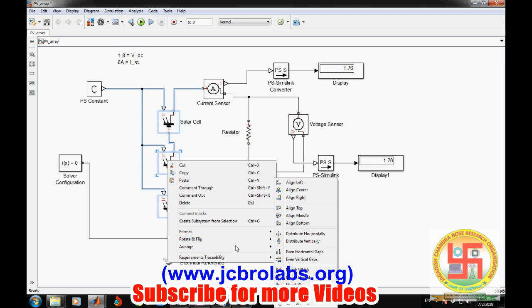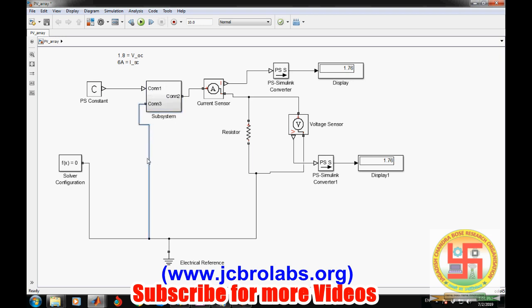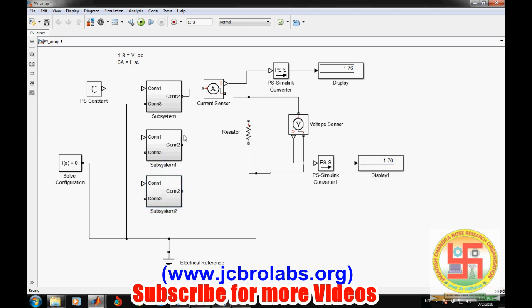Let's create a subsystem. Create subsystem from selection. So this is a solar cell panel which has these three requirements. Now let's say we want a larger amount, so let's create a copy of these subsystems. Each subsystem was providing 1.8 volt open circuit voltage, and now let's create something bigger.